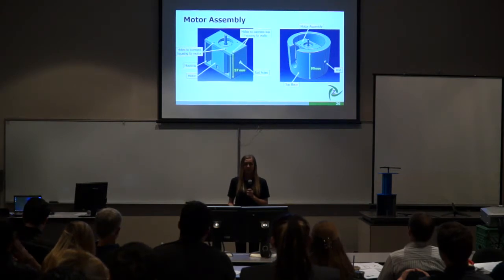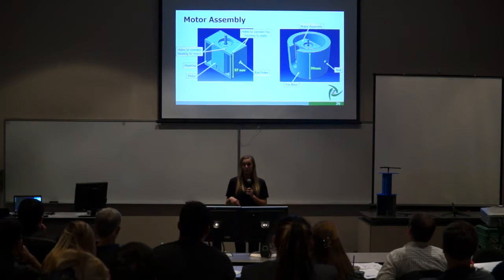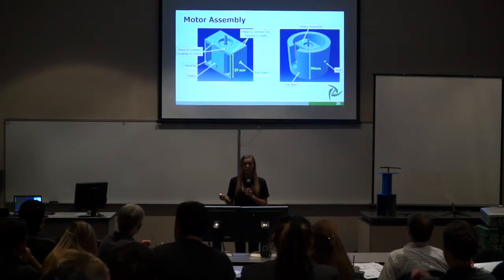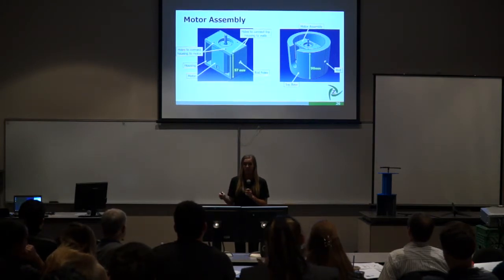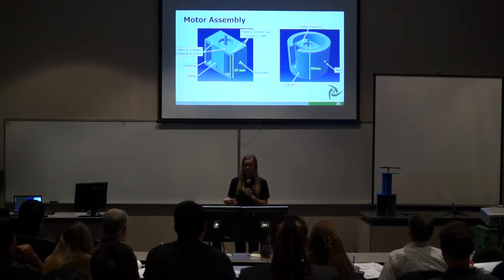The motor assembly consists of a motor housing and the motor itself. The motor housing attaches to the motor using 4 different screws at each corner of the motor. These screws will screw all the way through the motor and through the housing. Then on the sides of the housing, there are 2 holes for rods to be attached. These rods will then go through the outside of the top base, where the user will be able to turn these rods to rotate the motor.